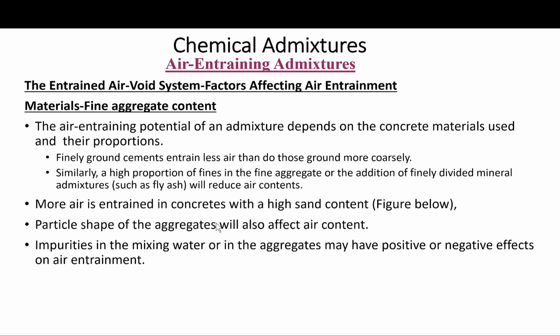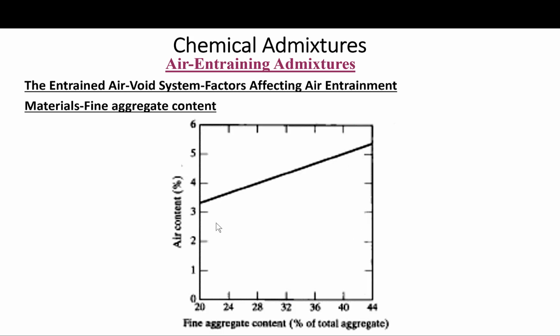And again, the key is to verify all this with proper testing, doing trial batches, to ensure any possibility is known and mitigated before you go on with bulk production. This is what I talked about here, about the fine aggregate content. As we can see, as it increases, the air content of the concrete mix increases.